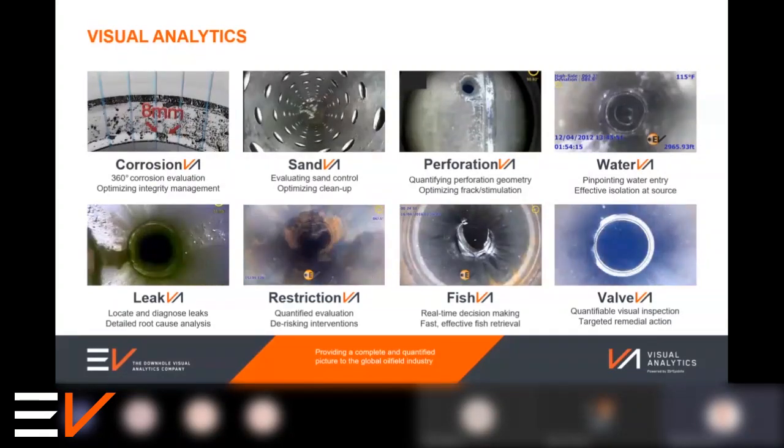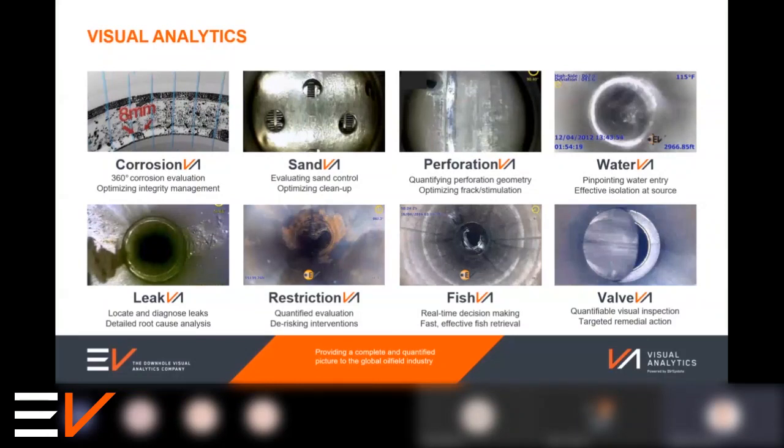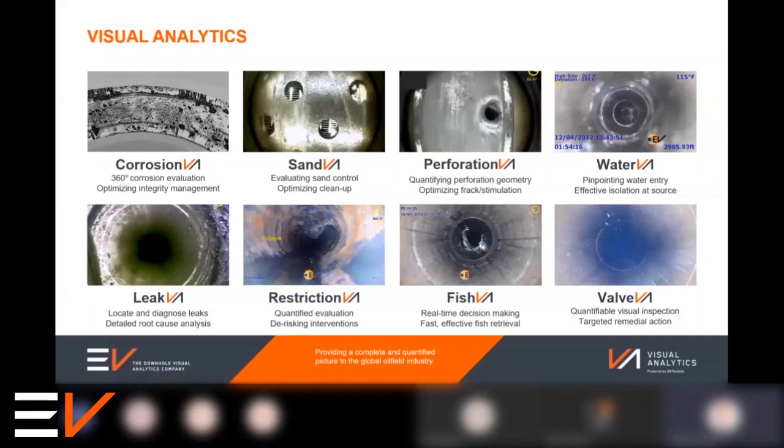And for a simple wire wrap screen, yeah, you're right. The wire would probably give way before you've got the erosional effect on the base hole. But we may actually be able to see the presence, or more likely absence, of that wire wrap in the event that sand has broken through in that location.